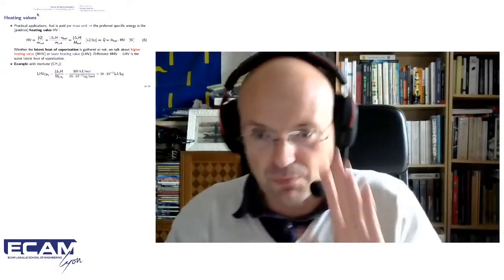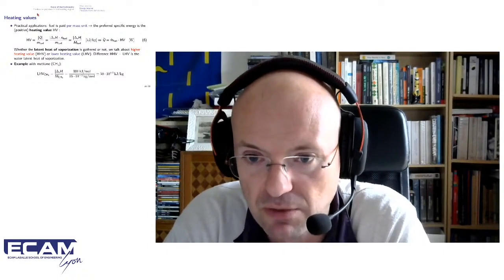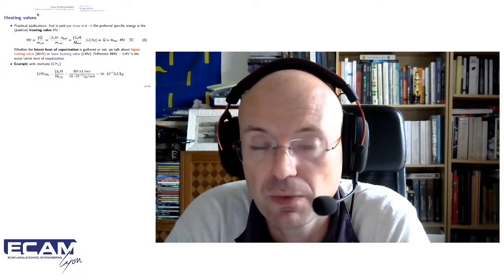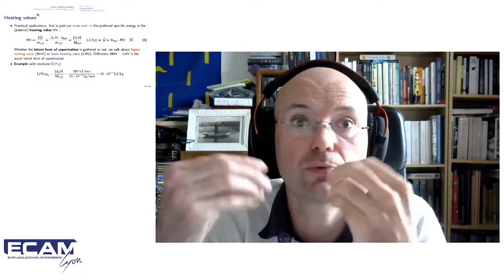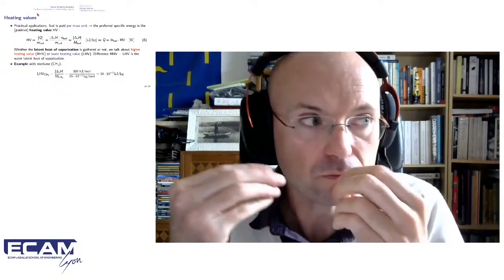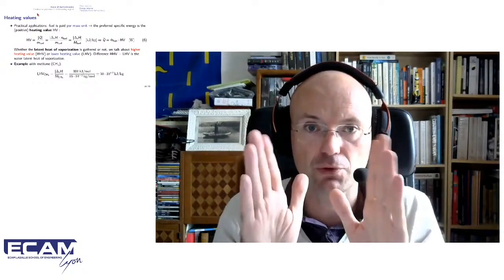Okay, now another detail. It's not really complicated, but you will need to focus for a few minutes. As I already explained, in any kind of combustion reaction, and specifically those involving hydrocarbons, the first component in quantity produced by the reaction is water. So your reaction is producing water vapor. If you reject this vapor directly into the surrounding air, and you just use the heat produced by the reaction, you will have a specific value of the heating value. It's the basic heat released by the combustion of 1 kilogram of fuel.